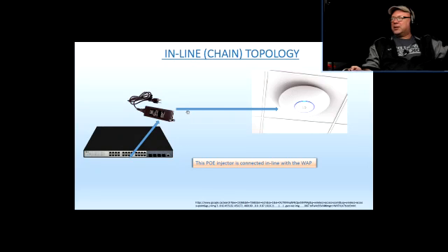So what happened is that with power over Ethernet, the Ethernet cable, the computer data cable, is capable of carrying not only signal, but also power to the device. So this is the DC power, and over that DC power, the signal is superimposed onto that. And the circuitry over there is just going to distinguish that. It's going to take the power and power up the device, and it's going to extract the signal from that line and use the signal to communicate between it and whatever it needs to communicate.